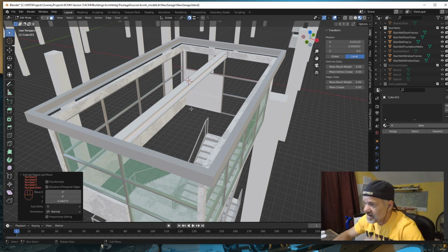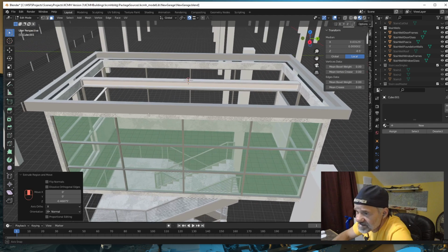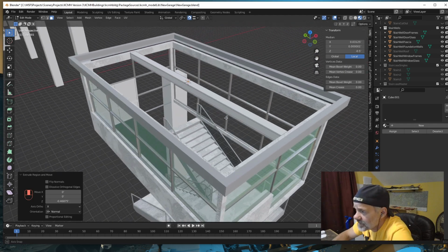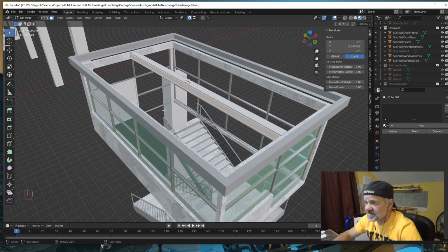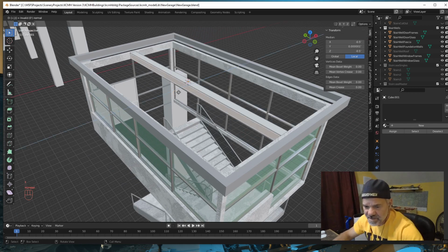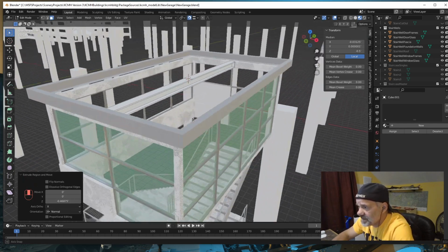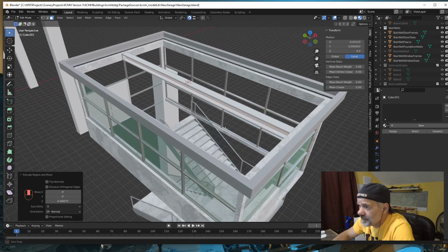0.46875. So that insets that steel inside. Now I come back over to the other side and do the exact same thing. E minus 0.46875. And that gives me an I-beam. Alright.